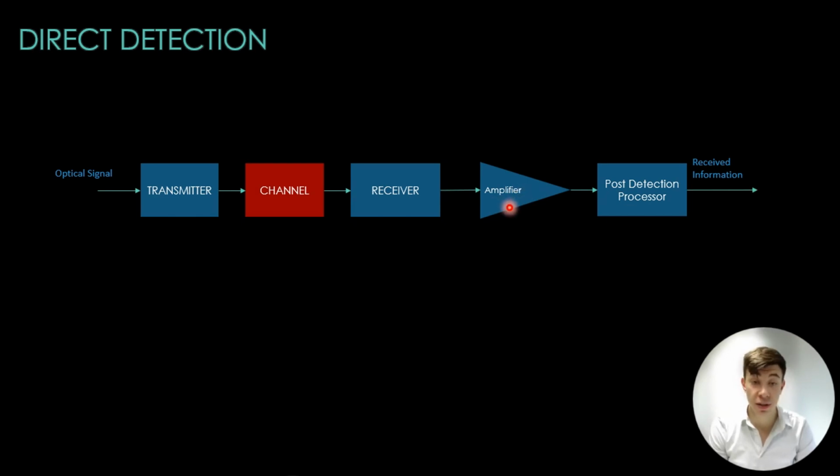So, key advantages are simplicity. Direct detection receivers are relatively simple in design and implementation, making them cost-effective and reliable. Maturity: the technology is well established and widely used in various optical communication systems. It's compatible with common modulation schemes like OOK, which are widely used in FSO.